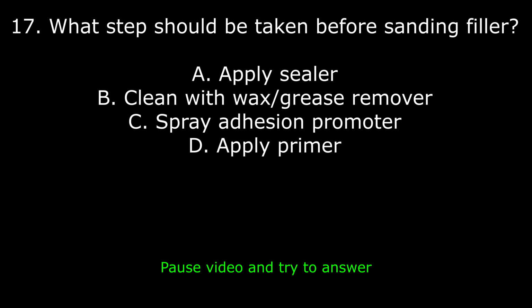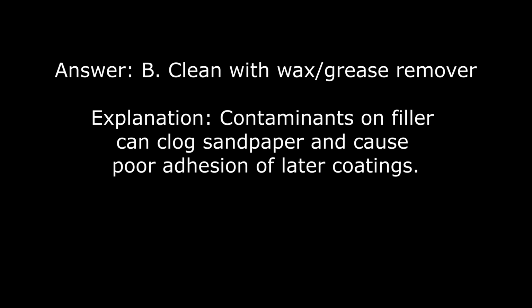Number 17. What steps should be taken before sanding filler? A. Apply sealer. B. Clean with wax or grease remover. C. Spray adhesion promoter. Or D. Apply primer. The answer is B. Clean with wax or grease remover. Explanation: contaminants on filler can clog sandpaper and cause poor adhesion of later coatings.